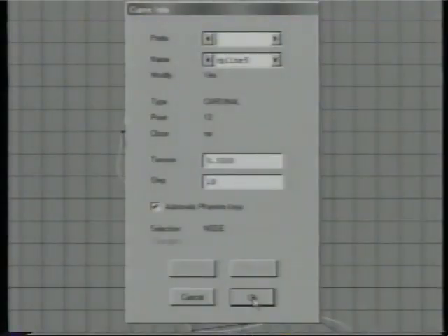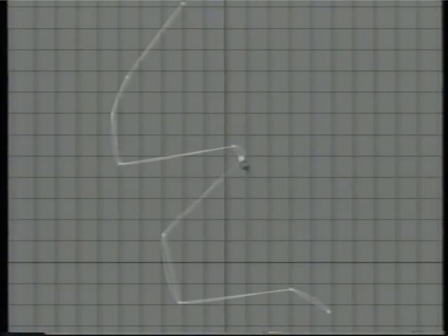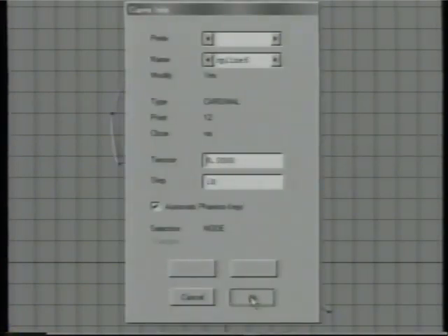Now in its dialog box, under Info Selection, you can change the tension, the overall tension, not for each point individually, but for the whole thing. So for instance, if I change it to 0.9, you can see how it overshoots more. And if I go back into Info Selection and set it to something really low, you can see how that changes it. If you wanted to create a hard edge with cardinal, let's set that back to the default of 0.5. Instead of bringing them very close together like that, you'd bring them near to each other, and then you could create what in NURBS you would need to drag the points almost on top of each other, if not overlapping a bit. So again, the drawback is that your nice hard edge can be ruined by the next node down the curve.